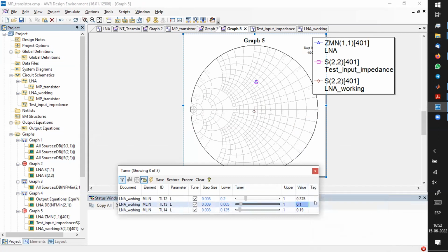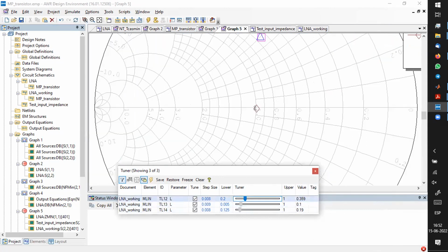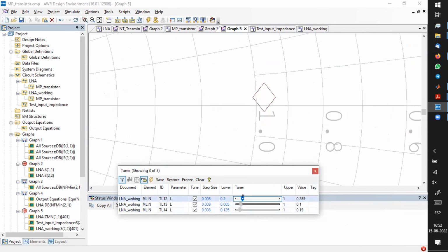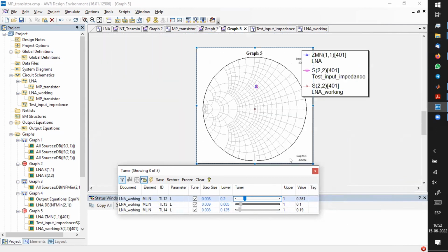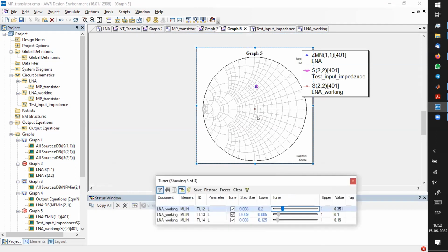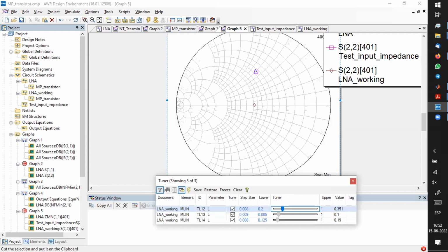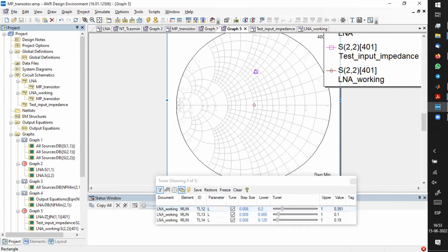It moved a little bit. It's like a shunt capacitor actually there. But it's close. Don't worry, it's a wideband design. We will need to anyway tune it a bit. That's 1 point. Yeah, so now it works exactly at 40 gigahertz, I guess. So if you now do a frequency sweep for your LNA, let's see how it looks like. Might not look very good yet.